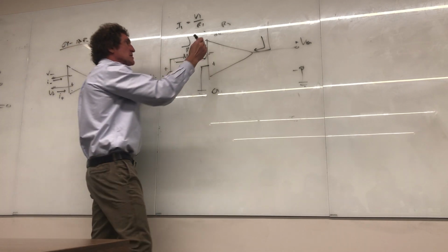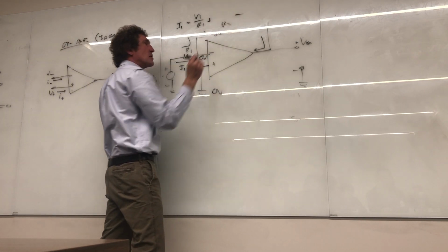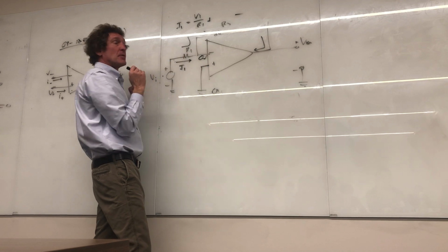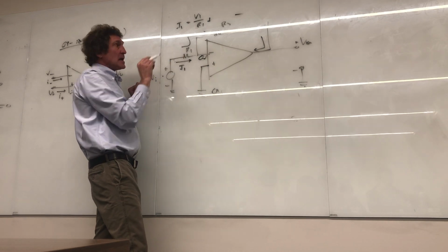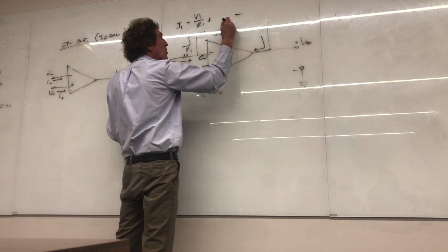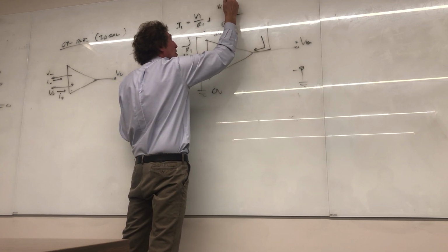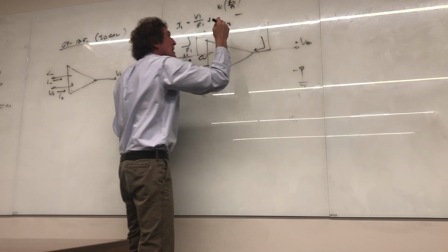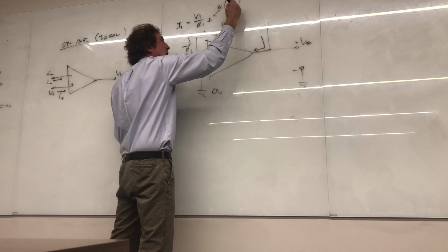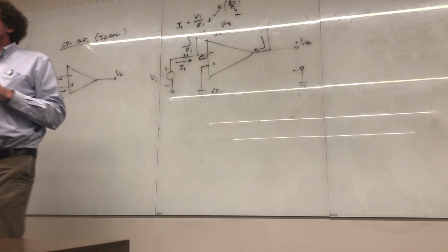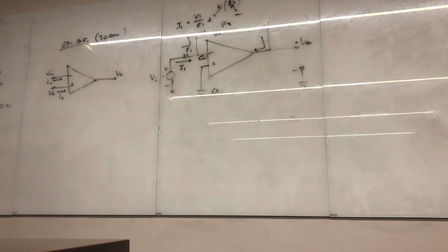Now, if I take a look at this, what's the voltage developed across R2? It's the current flowing through R2, I1, right? Times the resistance R2. Or the voltage here would be VI times R2 over R1. That's the voltage from here to here across it. Do you all see that, class? Can I get a show of hands to make sure everybody sees? You see in the back? Over here, guys? I'm doing my best to try to make this simple.